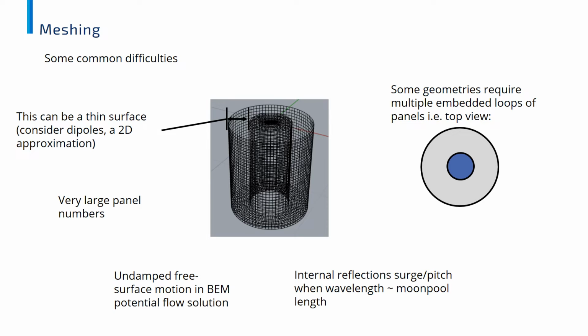And because we're solving this in the context of potential flow, which does not model the vortex losses or any other sort of viscous loss that would be associated with large amplitude motion, the predicted responses within potential flow of these resonant modes are going to be very, very significant and dominate the presented dynamics, when in fact, of course, they are non-physical because they'll be subject to significant damping forces in the real world.